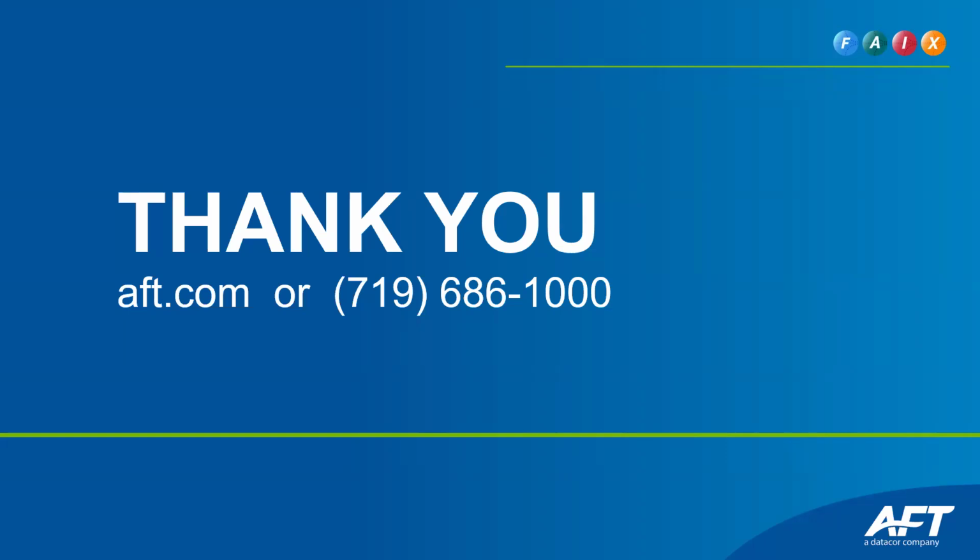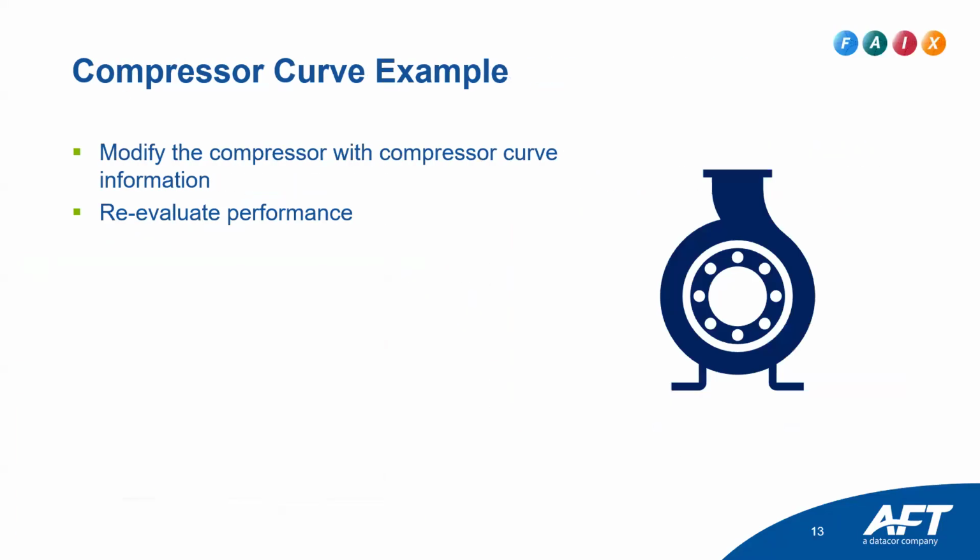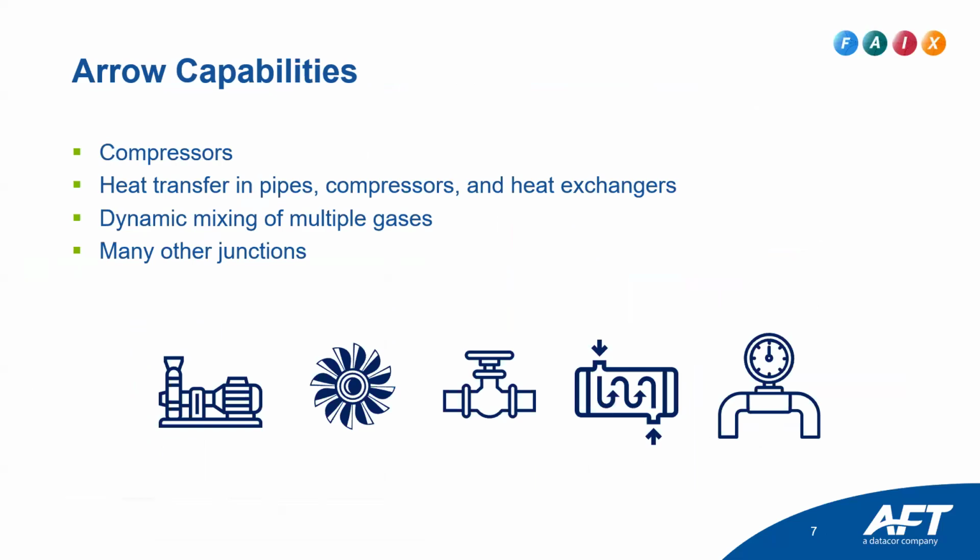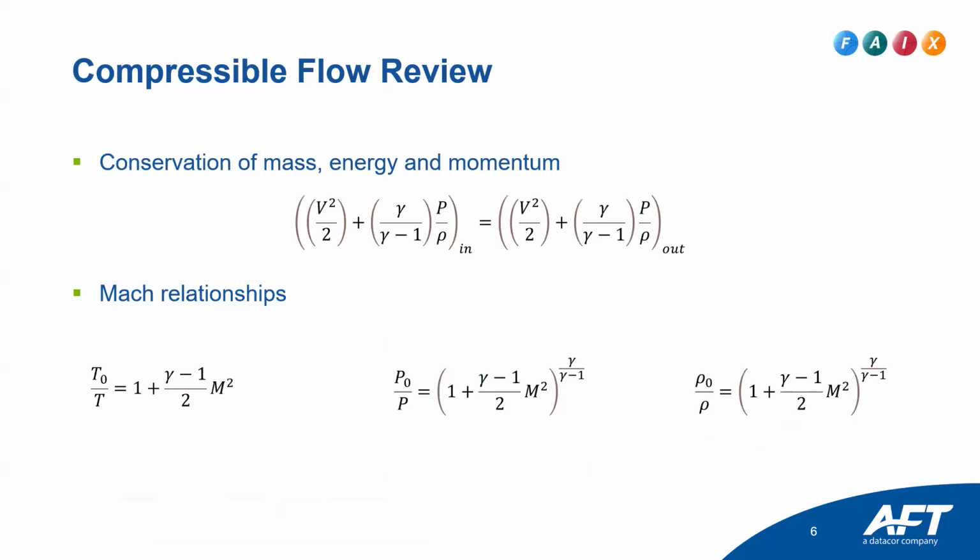Are you using static temperature? Is there any difference? Yeah, they are going to be quite a bit different, because of this relationship. The closer that you get to Mach equals 1, those are going to be different. We were just using static temperature because that's usually what you're measuring if you have thermocouples. But yeah, you could use stagnation temperature if you'd like.